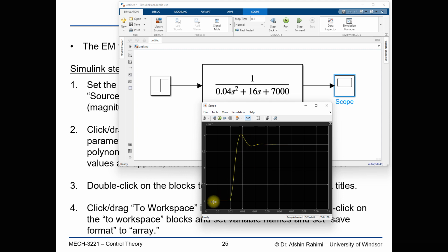And we see that we actually have at 0.02, we have an input. The input causes the system to react, so it will start to change its value. It overshoots above its settling value or set point. Then it comes back down, oscillates, and then gets to the set point. We also can see that we actually have still a coarse response, meaning that it's not refined, it is not smooth. And this is not really how the system should behave.